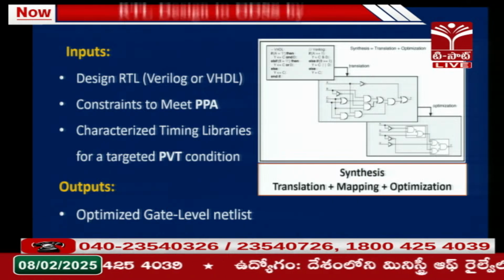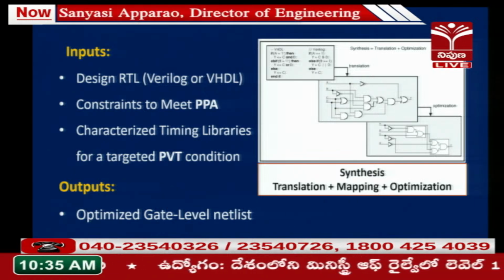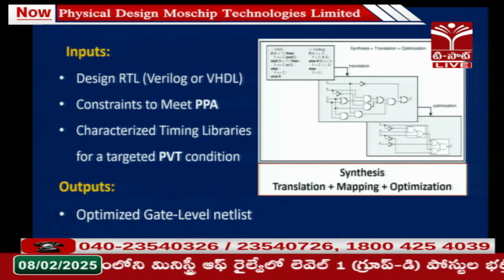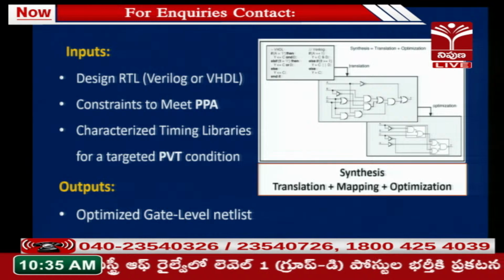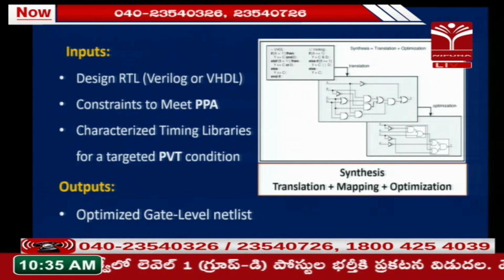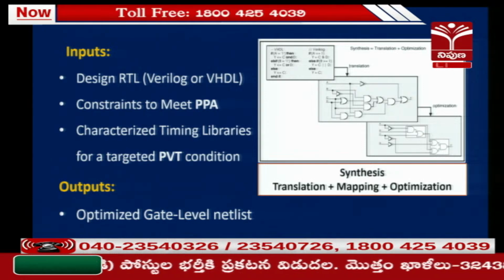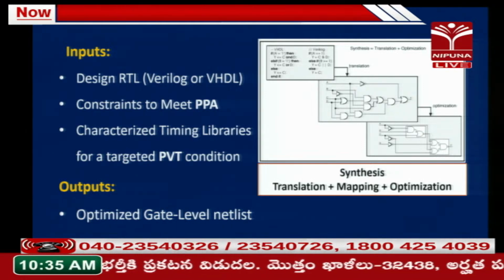Okay? And in a typical corner, let us assume that each cell delay is 1.5 nanoseconds. And coming to the fast corner, where you are seeing fewer delays, let us assume 1 nanosecond for each gate. 2 nanoseconds in slow corner, 1.5 in typical and 1 in fast corner.